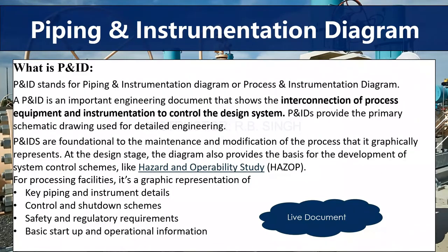So this is a live document. Whenever you start your engineering, you will start with the P&ID, and throughout the project, even after the project, in the running plant, the P&ID will be updated from time to time. Just like whenever we move a piping or add anything in the plant, the P&ID will be updated accordingly.